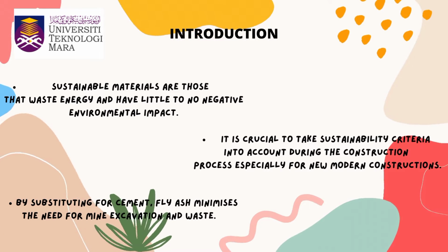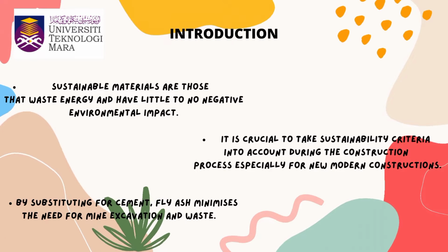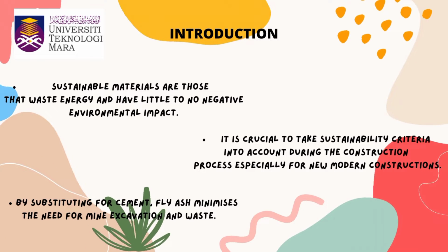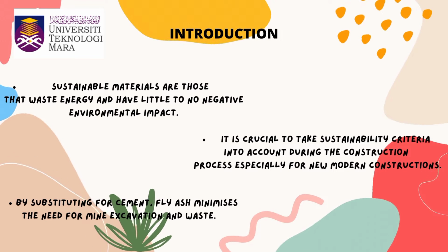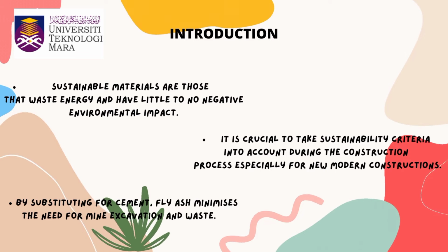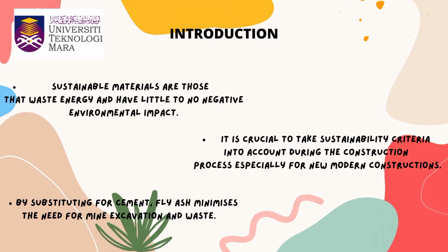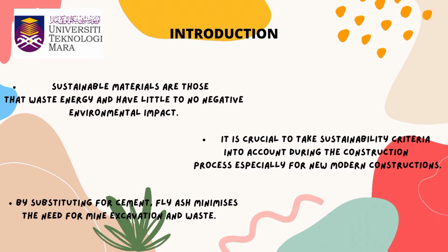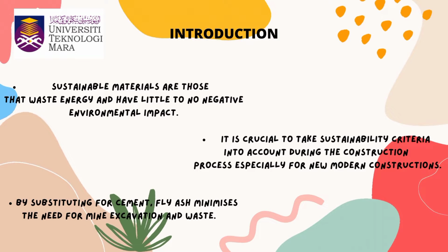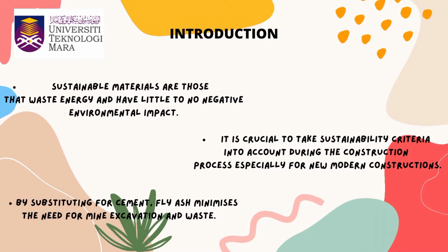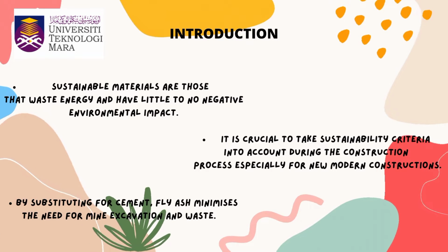Over 65% of fly ash generated by coal power plants is dumped in landfills and ash ponds worldwide. Outdoor ash storage or disposal can eventually cause harmful chemicals to seep into aquifers of groundwater. Fly ash generally enhances new concrete by lowering the amount of water needed for mixing and enhancing paste flow characteristics.